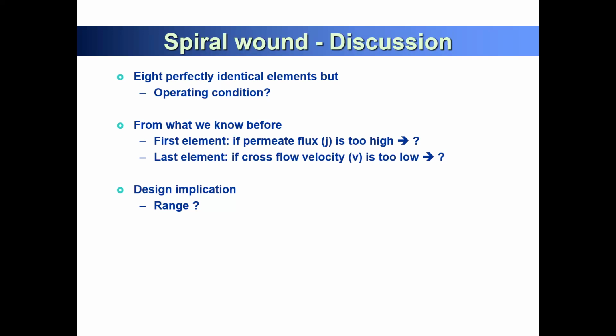Same as when you have a new membrane, you have very good performance. One year later, it is reduced by 10%. Two years later, performance is reduced by 30%. But unfortunately, this software cannot calculate all this kind of detailed fouling potential, as well as the aging impact.